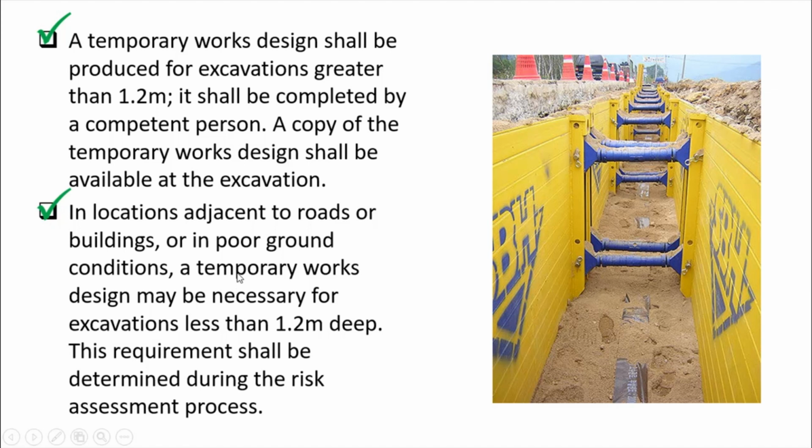This is to prevent the excavation from collapsing onto the people and also to avoid damage to the adjacent properties, and especially the vibration from the roads. Day to day, it will weaken the soil stability of the excavation if it is beside the road. So it is very important that temporary works design should be considered, and it should be prepared by a competent person or the structural engineer.